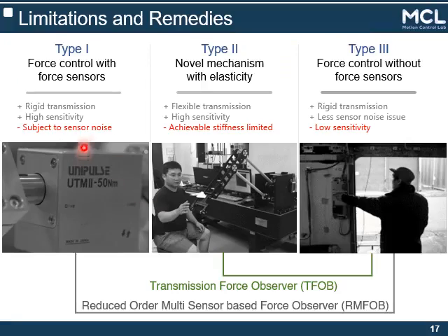However, each force control approach has its own drawbacks. Mostly, measurements by each sensing mechanism have limitations. For example, a force sensor is very susceptible to noise and offset, and it is not easy to realize highly sensitive force control, while the spring of SEA has the hysteresis issue. To overcome these limitations, multiple sensors can be utilized at the same time.